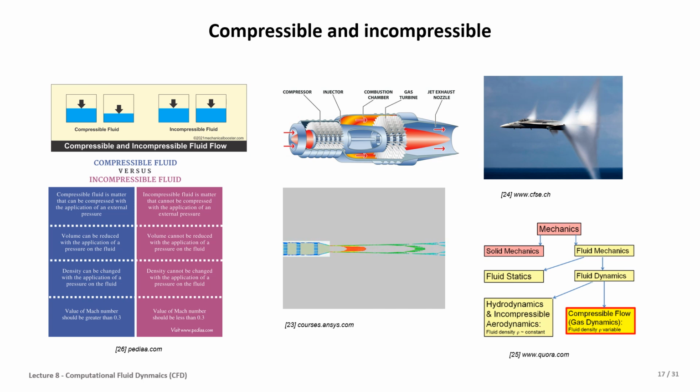In fact, it's leading to another non-dimensional number. It's called Mach number. When we have the fluid dynamic, the compressible flow is mostly about the gas dynamic. And when we are dealing with the hydrodynamic and incompressible aerodynamic, with Mach number less than one, we can say it's incompressible flow.